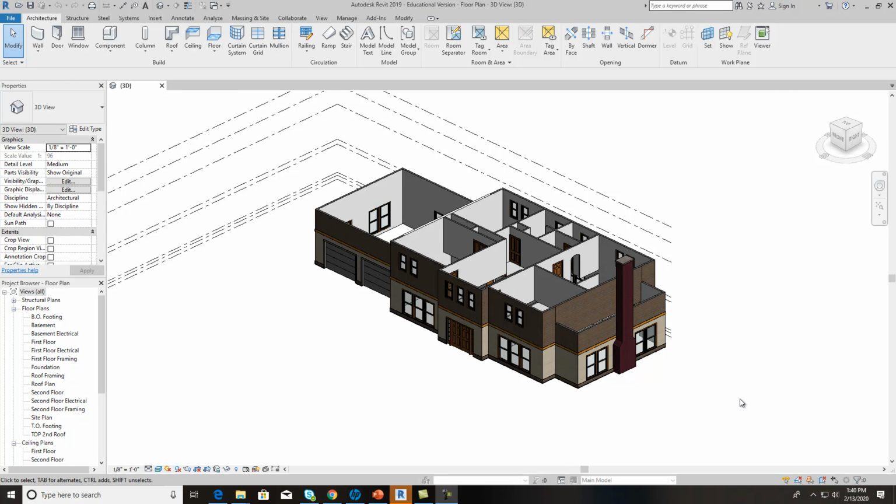Welcome back to CAD 216, and we're going to put a basement on this one and work on the foundation. You'll see in the book, but around the perimeter here, around this section right here, minus the garage, you're going to have 12-inch thick concrete walls and the footer underneath, and there's not going to be a basement on this portion. It's just going to be a footer, or your foundation is going to go down with a foundation wall of 8 inches. Now, you'll notice something on here.